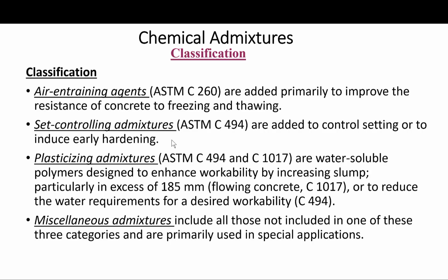They are water-soluble polymers designed to enhance workability by increasing slump, particularly in excess of 185 millimeter, or the flow in concrete according to ASTM C1017, or to reduce the water requirements for a desired workability. Basically, in this case, we reduce the water requirements or the water amount added.